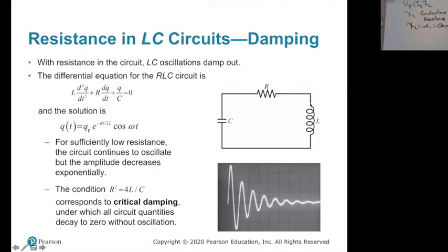If we take out this inductor, this thing would just discharge slowly over time. We did RC circuits back when we were talking about direct current circuits. Because we have this inductor in here, we're going to end up charging the other side of the capacitor, which will then discharge going the other way.